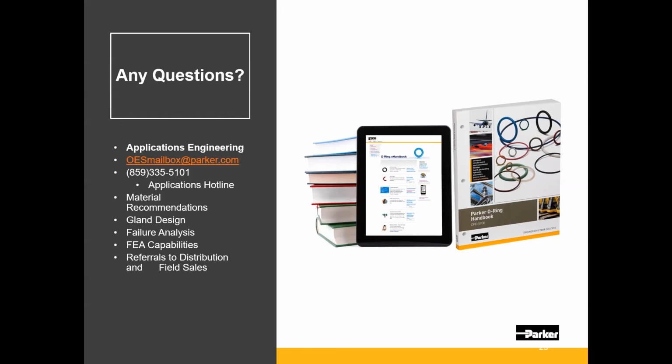Outside of an O-ring, there's a number of seal options that would not spiral fail or would be much less likely to. Some of those might be any kind of a seal with a wider stable base, not a round base, for example, like an X-ring or maybe a D-ring, anything that would not have that tendency to roll. Those are some alternative options for preventing spiral failure.